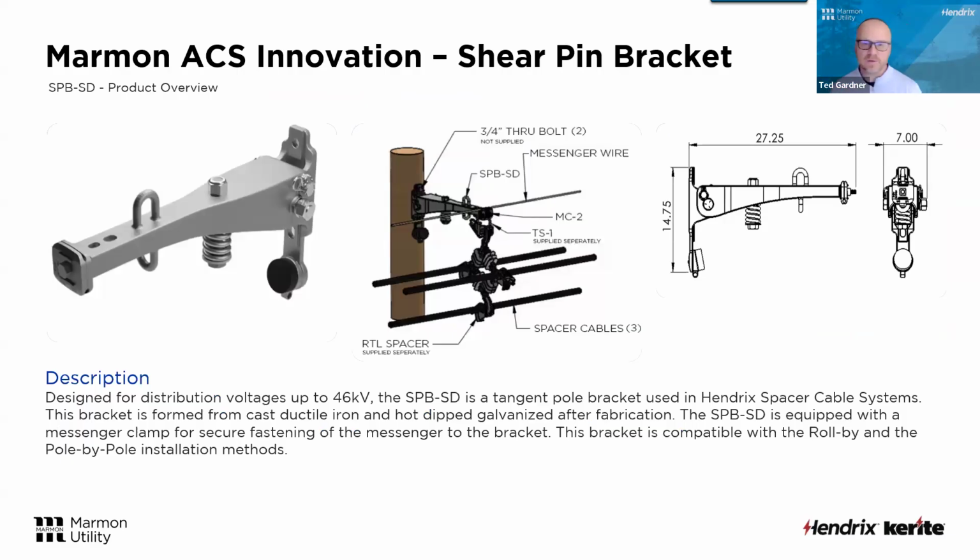The other thing, as I mentioned, we've always wanted to protect the poles as much as possible. And a lot of customers will report broken poles. So with a spacer cable system, one of the first things as an engineer, we take a step back and look at the size of the poles and the span lengths and how loaded up they are. And that usually is one of the culprits.